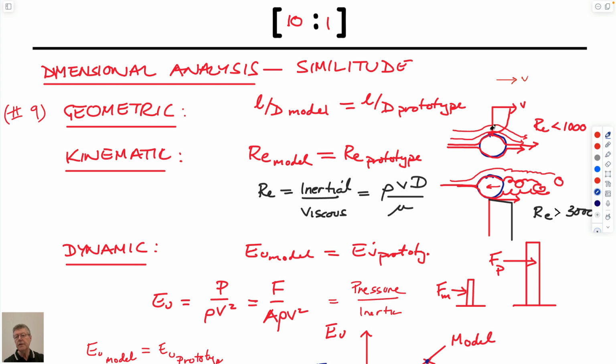And so by having this object in the flow field, you intrinsically change the flow regime. And at low velocities, Reynolds numbers less than 1,000, it would look like this, creeping flow. It hugs the system, and as you go progressively out from it, these get closer and closer to the far field velocity as you go further and further away.